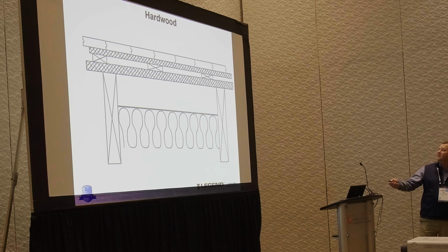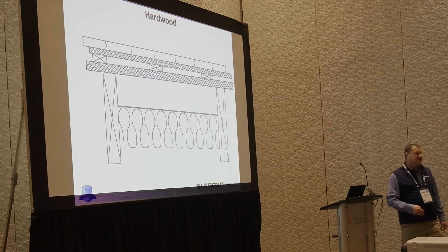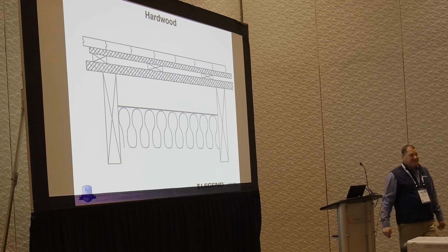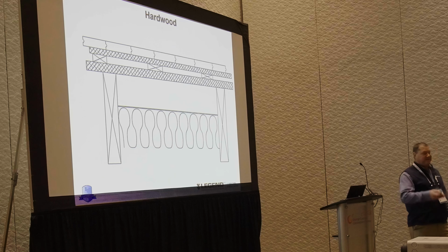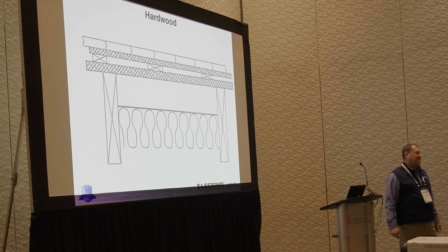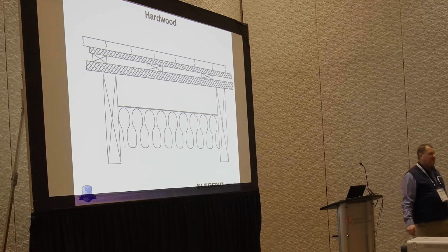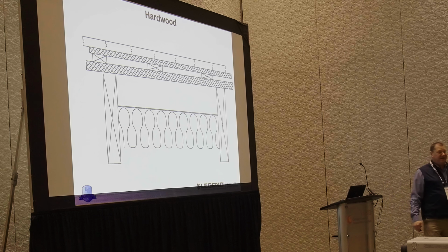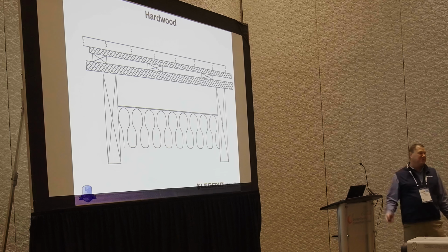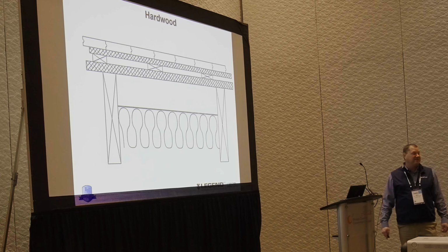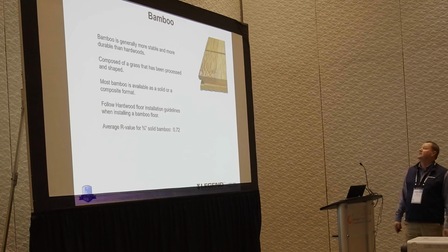But wouldn't you feel bad if you put in heat transfer plates, charged that customer all this money, you turn the system on, and you don't get the performance you want? Maybe with 180 degree water, it'll keep raising the water temp up, keep raising the water temp up, and eventually it'll heat. And that's not our goal as designers. We should know what the construction is of that floor before we commit to putting radiant in there. Especially if it's new construction, I would hope that wouldn't happen, but you never know. So you should always confirm what that construction is.